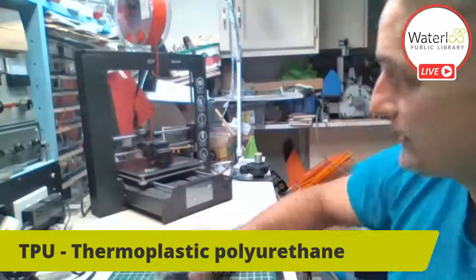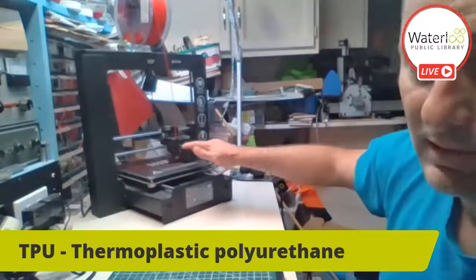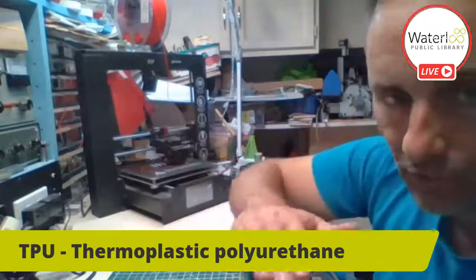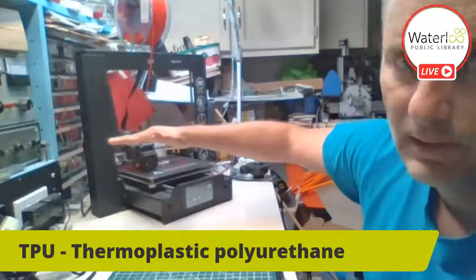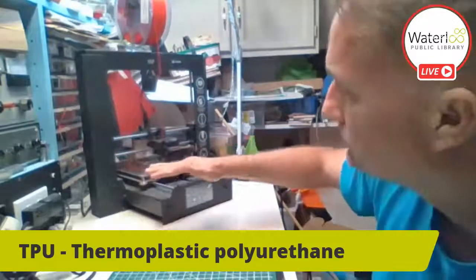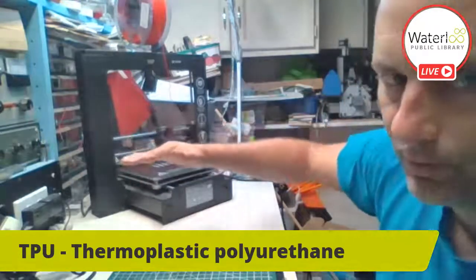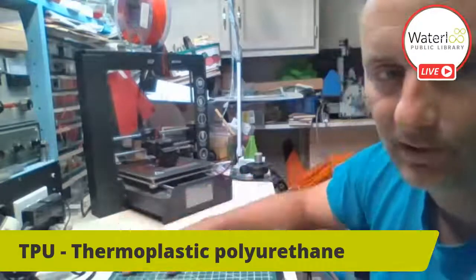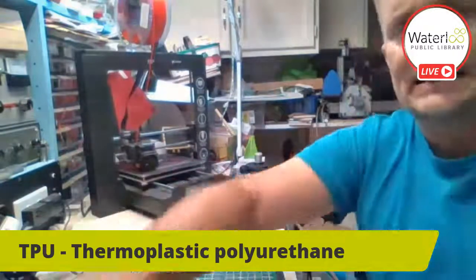And yeah, that's it. So right now, all it's doing is drawing the first layer, just one little thin strand of plastic at a time. Once it's finished drawing that entire first layer, the Z-axis will lift it up, I believe 0.2 millimeters, and it'll draw another one. And then once it's done drawing that second layer, it goes up again another 0.2 millimeters, and then draws that third layer, and it keeps going on and on and on until it's done. So that's it, I believe, for the 3D printing stream.